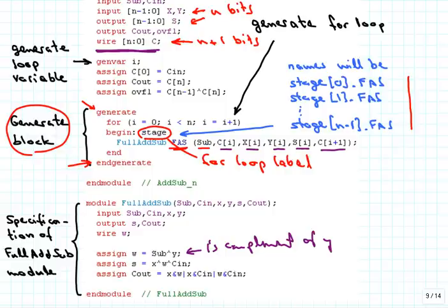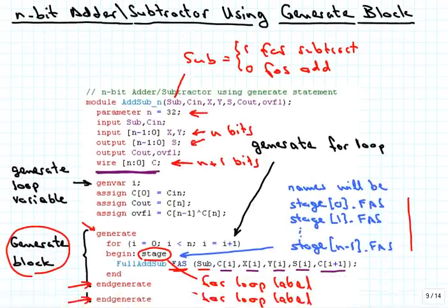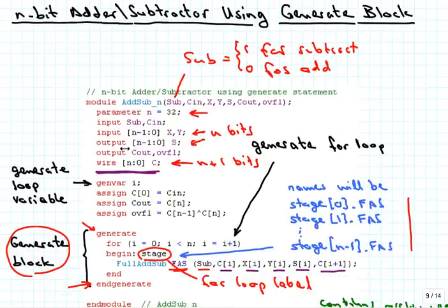So one thing to notice here is that we actually have been using continuous assignments throughout both of those modules. The generate, which instantiates modules, the outputs of that go into wires, because those form permanent connections. Those are not procedural statements. And so for our inputs and outputs, we have actually all wire signals. So none of those here, which we had declared at the beginning, or the intermediate ones, are actually of the register type.